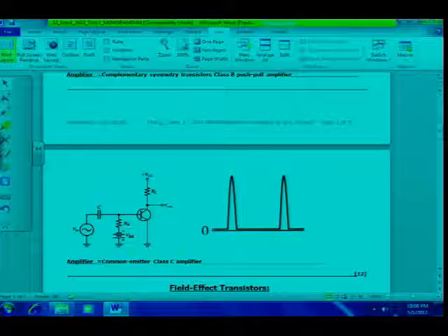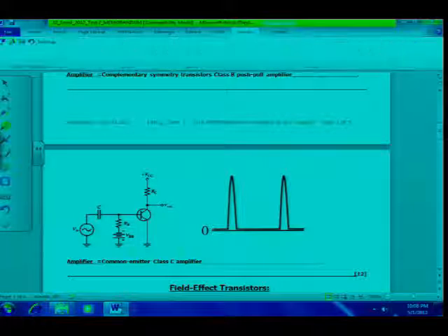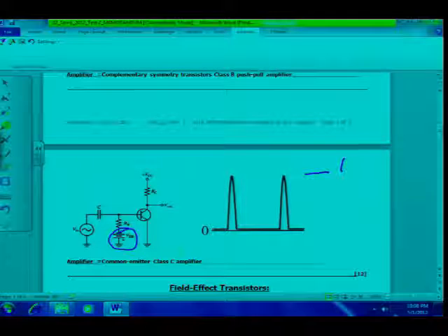Class C, of course, I can see that the amplifier is still negatively biased, so my input signal has to overcome the negative VBB and the 0.7 of the base emitter voltage. Now, you had to show clearly, because some of you made the mistake to draw this waveform. You've drawn something that is totally out of sync. But anyway, your on time